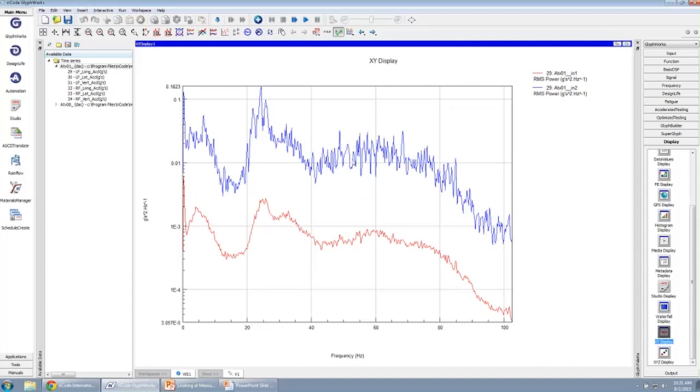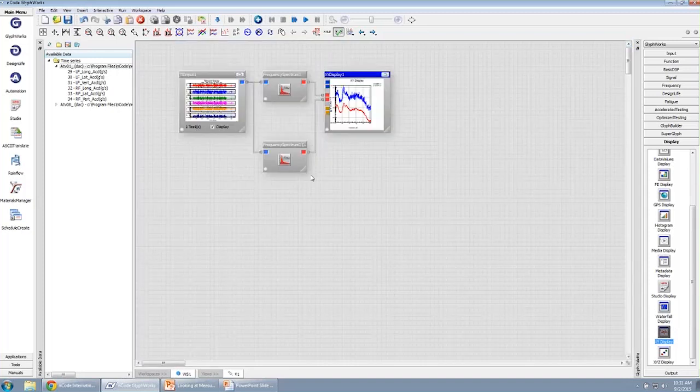So the peak hold is certainly going to be a worst case scenario. It is the worst frequency, for this particular spectral line right around 22 Hertz, seen in one of those buffered PSDs. Whereas this would be representing the average of all of them for that particular spectral line. All right, so there were a couple of things where we compared and contrasted.